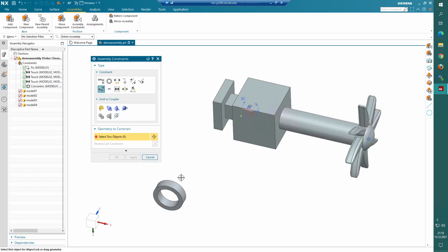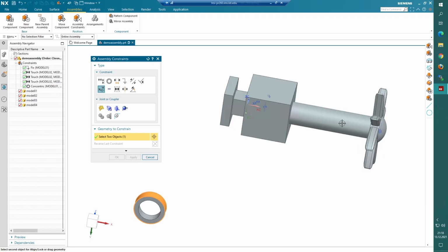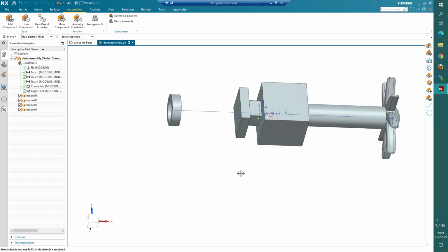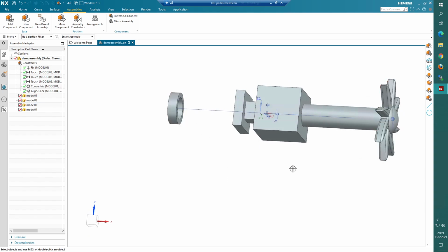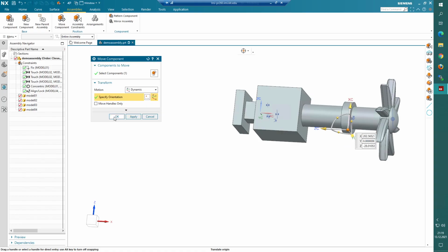And a little tip, it's always a little finicky to get to the center axis. You can simply click on an element like this, and then it will automatically select the center axis. And also we can just click on this element. And now you see what the difference between this constraint and that one is. That one laid it on top of each other, and it allows rotation. And this one is kind of almost the opposite. It also lays it on the same axis, but it allows for moving, but not for rotation, okay?